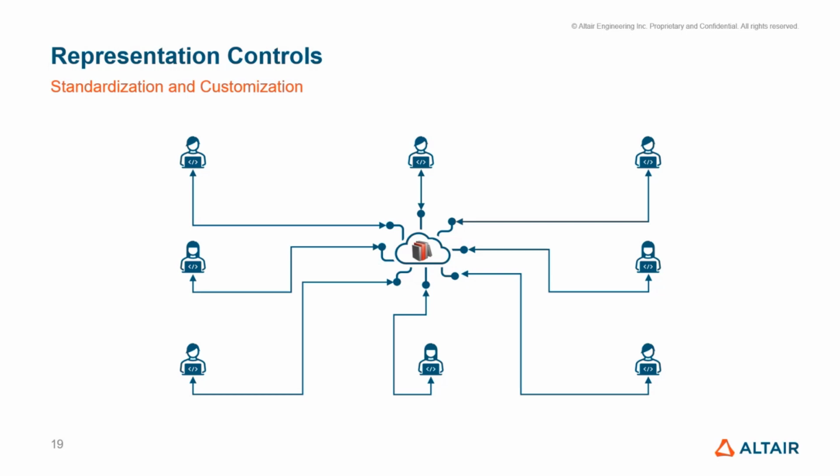The current implementation has a limitation regarding overwriting representation controls in the library, which is that once a control has been saved in the library with a specific set of values assigned to it, then if you change your mind and want to change some of these options on the control, it's not possible to push the changes in the library. However, you can still be using the updated control locally. It's just not possible to push the changes in the library. And this limitation is going to be erased in the future as well.